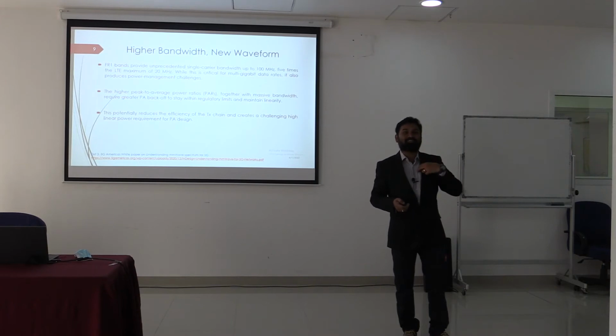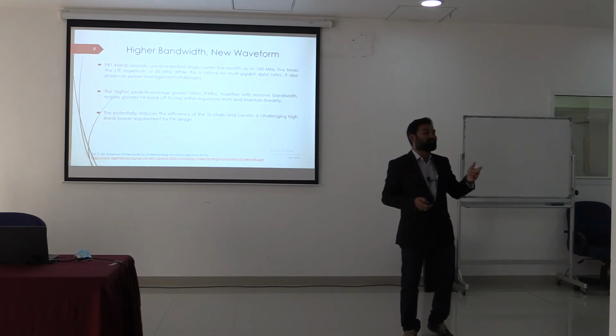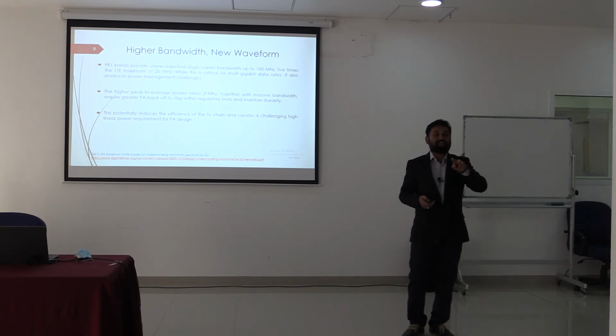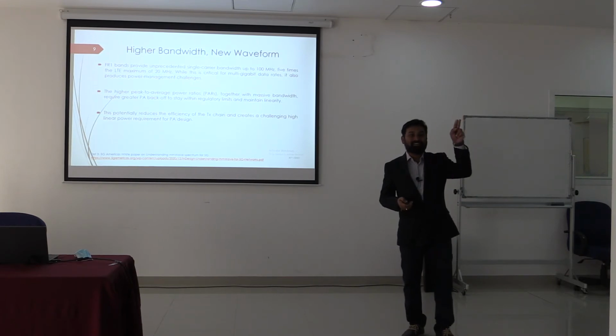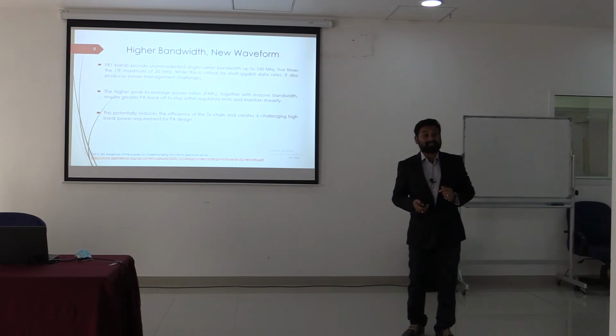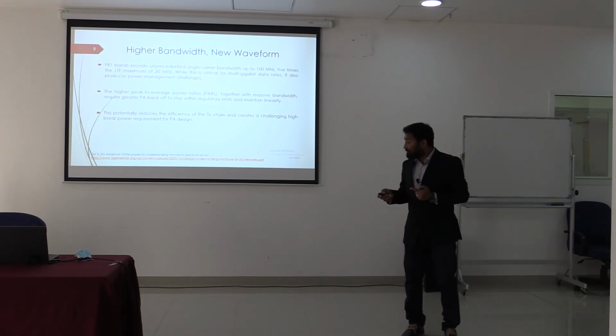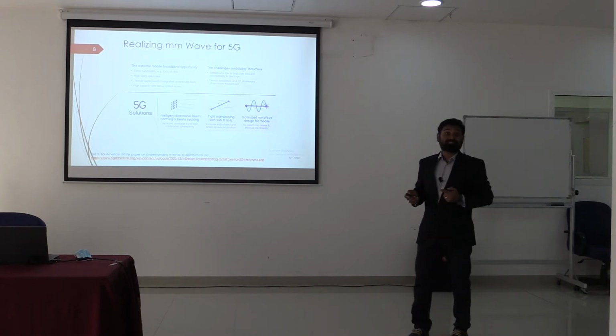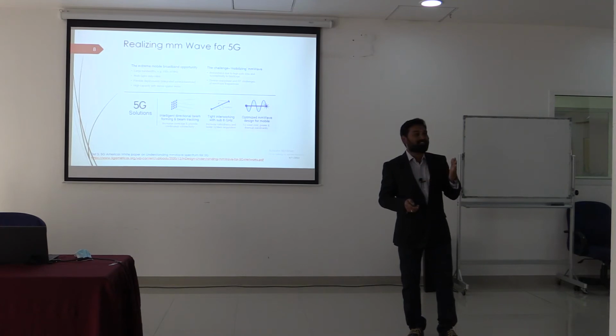Nowadays we are telling that my phone has the feasibility to work with 4G as well as 5G. My phone is a 5G phone. What is the limitation they have made? How have they brought this bandwidth increase when your gain will automatically decrease? It means that your service provider cannot provide much data rate to you at a far distance. So that is one of the critical parameters, as we mentioned here, the mobility of your millimeter wave. That's why when we say our phone is operating with 5G, it is not at the millimeter wave spectrum. Either it may be in the 700 megahertz spectrum or it may be in the 7.125 gigahertz spectrum.